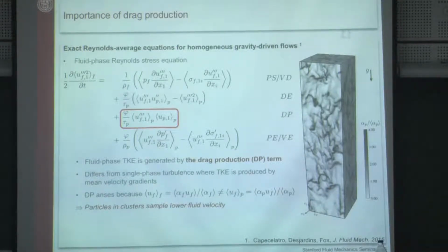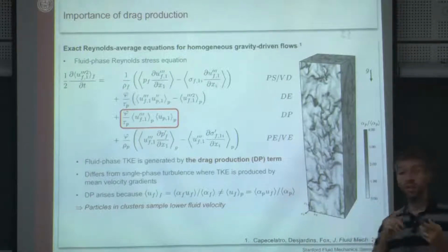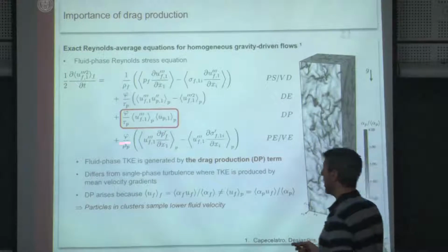So he's been deriving all those equations, basically applying ensemble averaging, or in this case, the flow is temporally stationary and spatially homogeneous, so we can average in all directions you want. Everything averages out. In fact, a RANS model should take the form of a simple algebraic model down the road. But anyway, you can derive those equations and look a little bit at what's going on. Why are those clusters here?